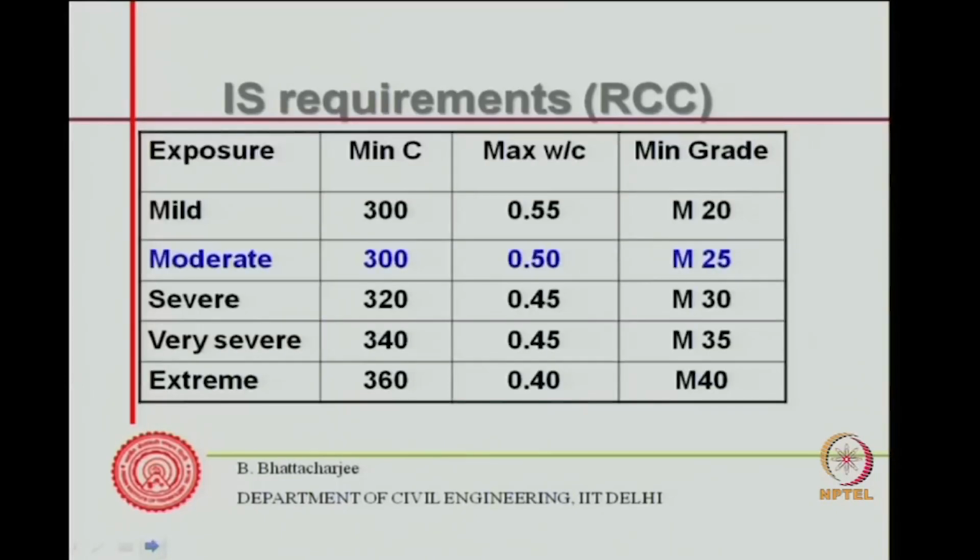Then it says that you use the water content from past experience if it is available, or if nothing is available, from Table 5 of IS 456-2000, from the durability requirement. This is the table which gives the durability requirement. And if you see the prescriptions, they are given for various exposure conditions: mild, moderate, severe, very severe and extreme.